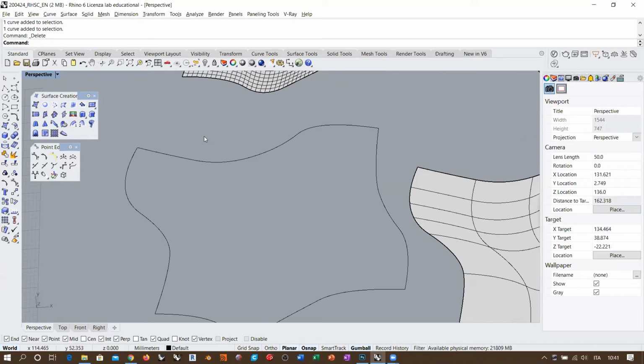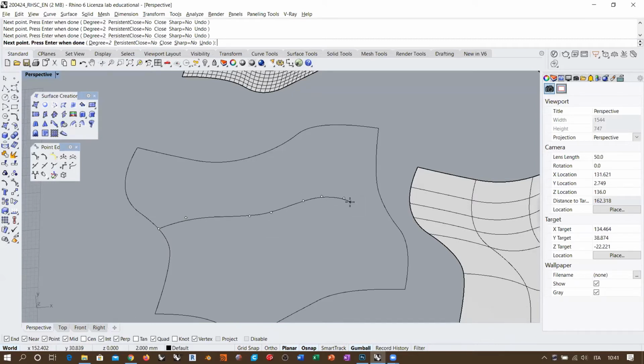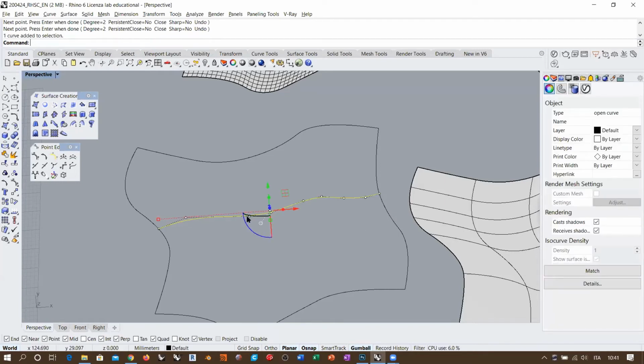the simplest topology that I would need in this case would be one control point on one edge, another control point to determine the initial tangency. Then I want this region of the surface to stay flat, so I need another two control points, so the surface will stay flat in the inner part of this set, right? And then I need three control points to reach a specific height. And then I need another two control points, like end tangent and end point. So a total of 4 plus 3 plus 2, so 9 control points, okay?